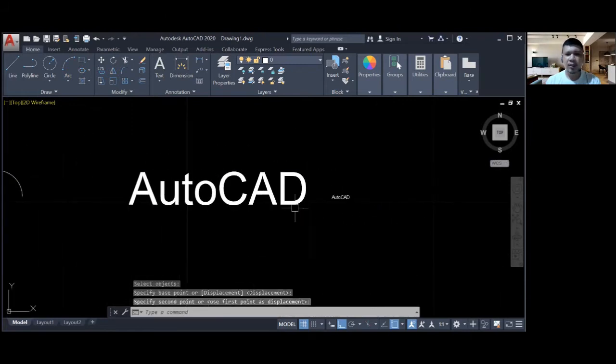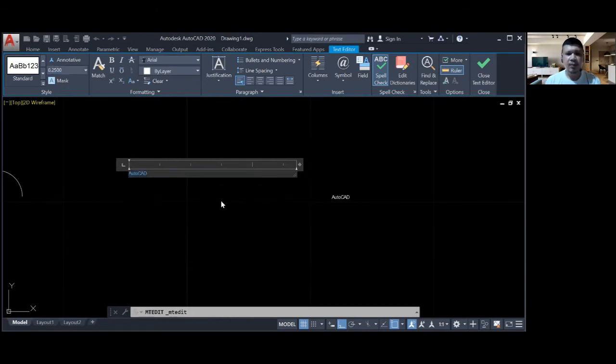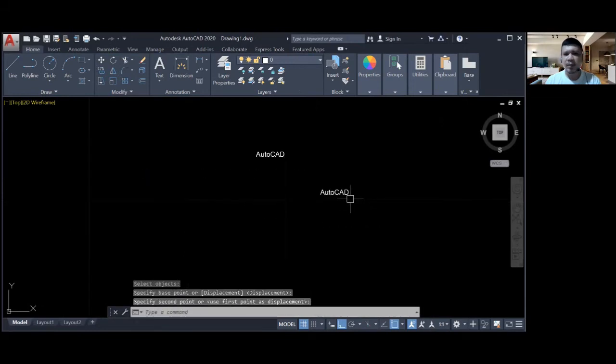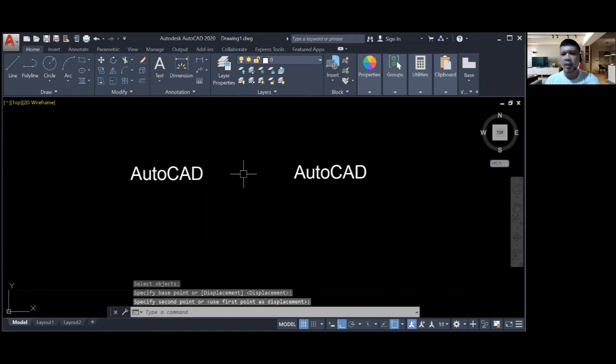Then change the text height of this one to 0.25. There you go. As you can see, they are not different in look. But when it comes to inserting, you saw that the multi-line text was faster to use compared to the single-line text. When you specify the exact location, I will show you how when we demonstrate how to label a floor plan.